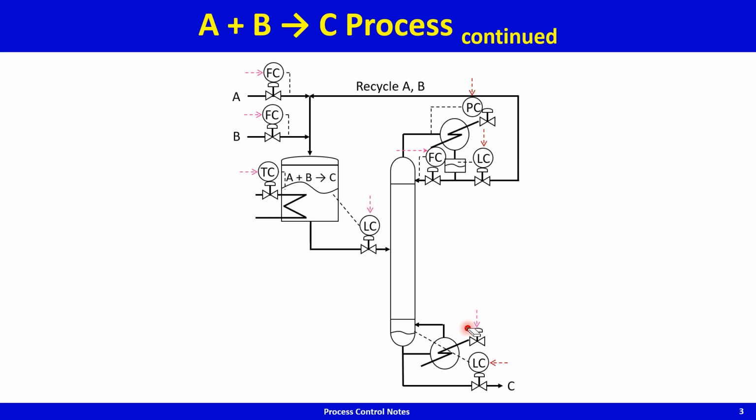So in this case, what are my specifications? I am specifying FA, FB, T reactor, level reactor, L, which is reflux rate, column pressure, reflux drum level, sump level, and reboiler duty. So the specifications are FA, FB, T reactor, V reactor, L, Q, P col, V reflux drum, and holdup in the sump. These are the specifications.